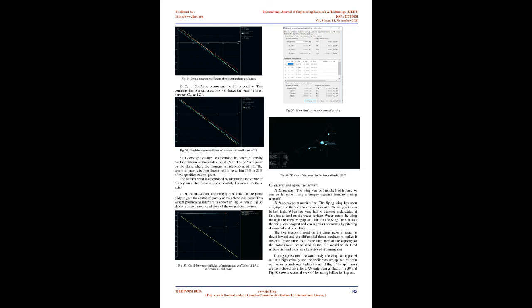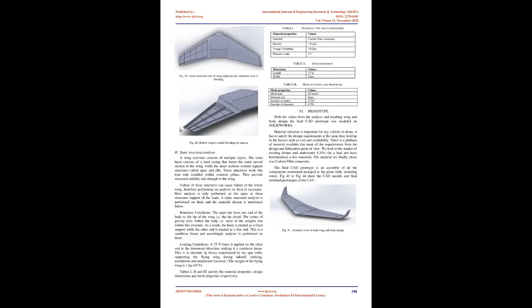The pressure gradient is another important performance aspect. It depicts the pressure range over the whole plane. From the legend it can be observed that the value of Cp is highest at the front, when the plane engages the fluid, with the Cp value decreasing towards the end and at the winglets. It also shows how, due to the much higher velocity at AOA 0, the pressure over the whole plane body is much higher compared to the plane at AOA 2.5.